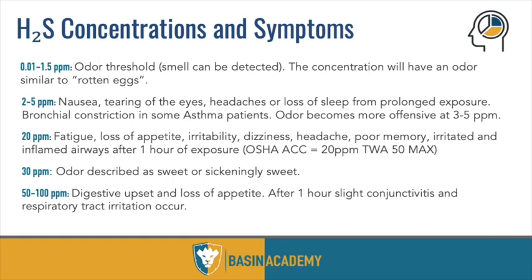Now, at 100 parts per million, that's what we consider the IDLH, or the immediately dangerous to life and health. I'll get into that in a little bit, but that's where we're going to start to see some more permanent damage from the exposures at those concentrations. So above 100, between 100 and 1,000, depending on who you are, it's going to affect you differently, but that's where we start to see unconsciousness, the lungs starting to fill with fluid.